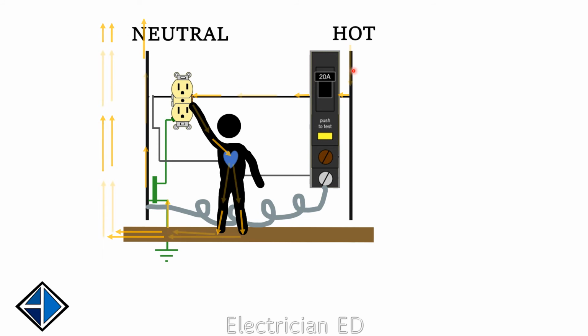In a normal situation, we would have something plugged in here, and it would come back through this neutral wire, back through the mechanism inside here, and then back here and up there. And if everything was balanced, it would be fine. In this situation, we've got power going through the circuit, but not returning here. So it's going to trip, and it'll do that within milliseconds.